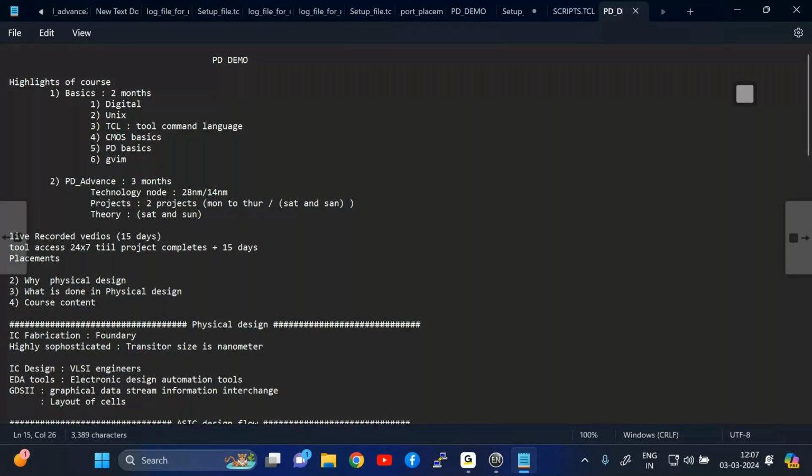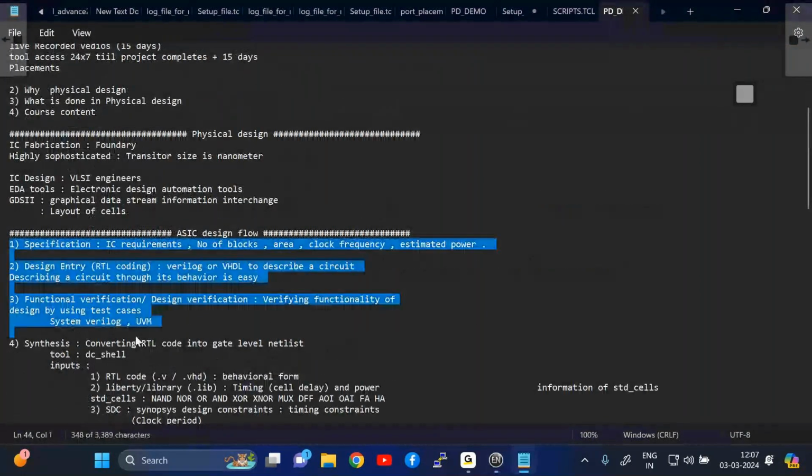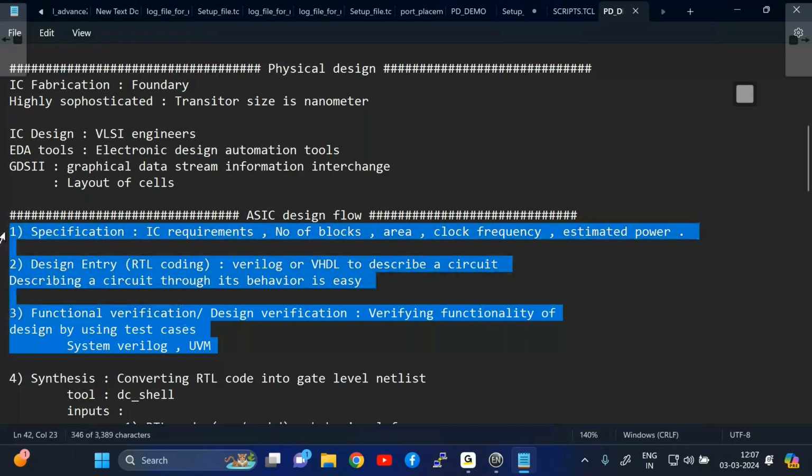For example, someone will ask, I want this type of protocol to be written and tested in these two processes, like the RTL specification, RTL code, and functional test. After doing this functional test, they will release that code. It's called soft IP.